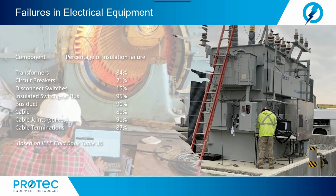Now, most failures of electrical equipment are the result of a breakdown in the insulation system. Power factor testing is an effective way to detect defective electrical equipment insulation. Power factor is the ratio of the capacitive or the charging current, measured in voltamperes, to the resistive or leakage current, which is measured in watts. It is a means of measuring insulation integrity, since the smaller the power factor, the better or the more efficient the insulator.